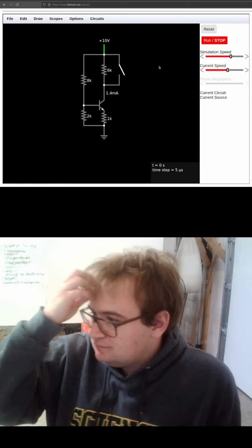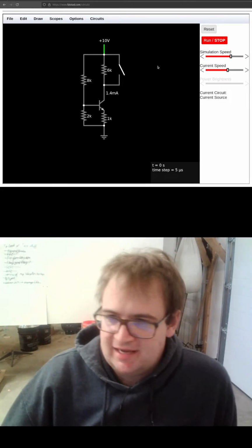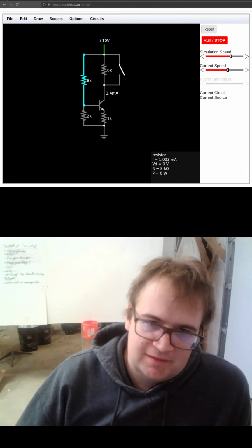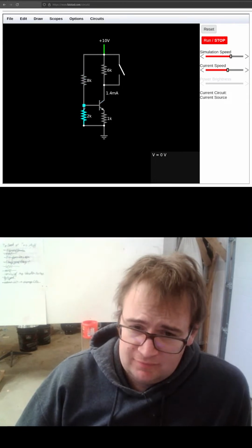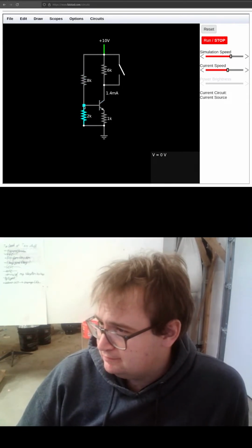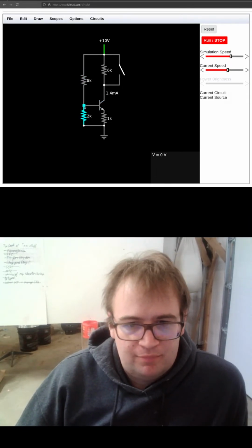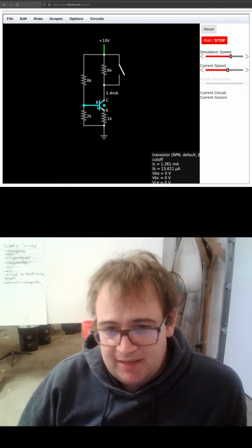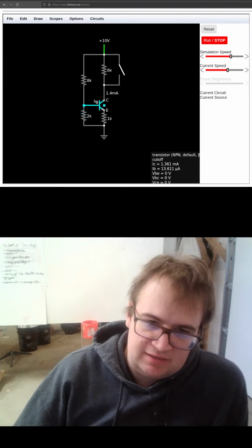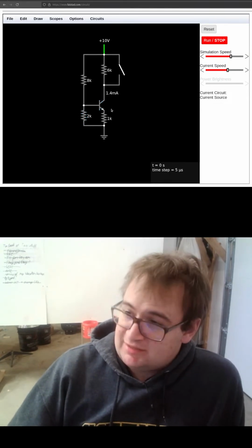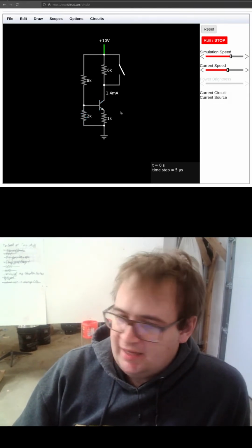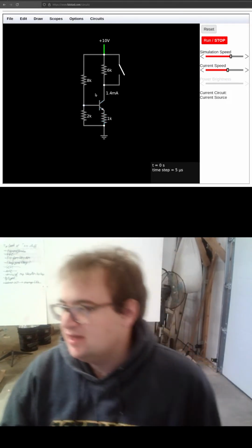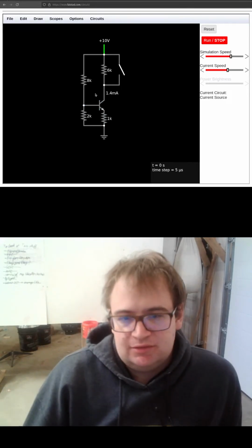Sorry, disregard what I said. What I was thinking there was incorrect. So at this point, we're gonna have 2 volts. Now that means we're gonna have about 1 diode drop between the base. Well, the 2 volts here doesn't mean we'll have that. It's just that transistors will have 1 diode drop between the base and the emitter, approximately. So say about 0.7 volts.